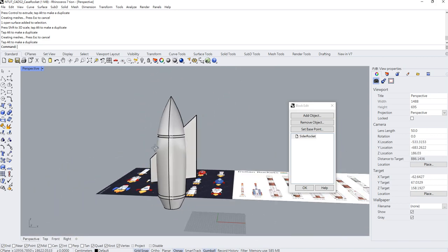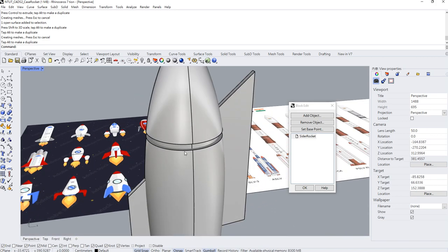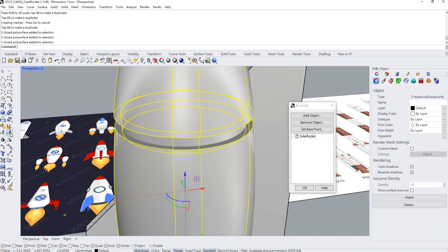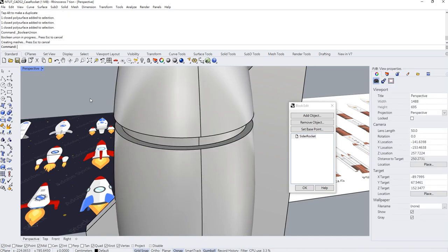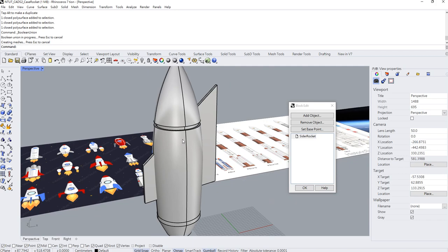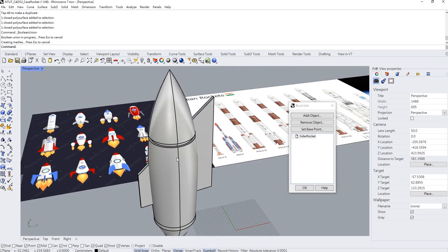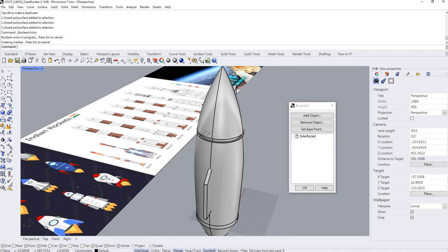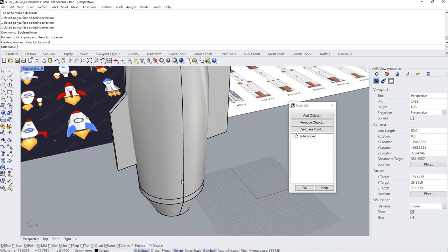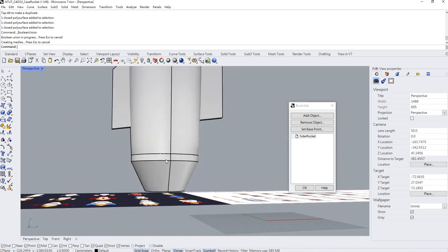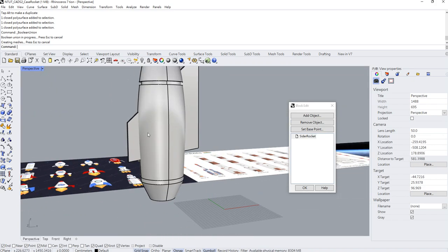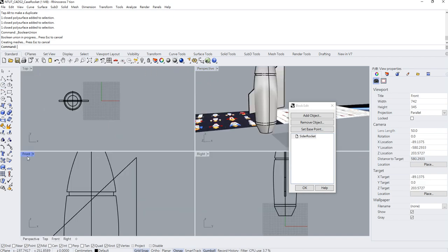For the rest of the parts, we can use the same way, but first I want to join them together. So let's use Boolean union to join them together. I also want to create a linear segment in the bottom area. How can we do that? Very simple. First, before we do that, I want to separate the injector part, just repeating what we did before.